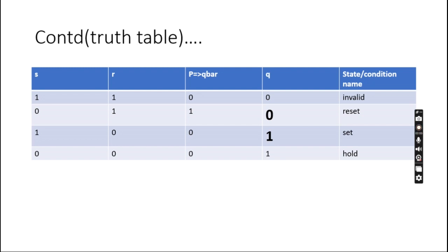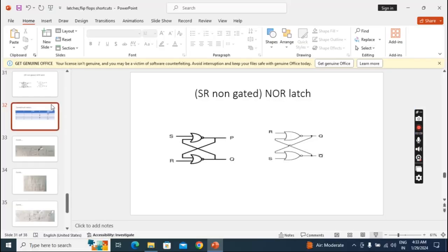So here in a NOR latch, if we keep this circuit at 1 1, when we apply input 1 1, it will be invalid. So whenever we want to make it useful, we have to change the input values. And one more reason: suppose initially I apply 0 0 to the NOR latch, what will happen?